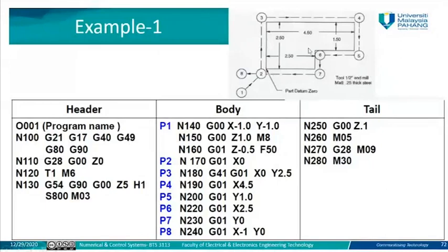Then for this part, for example, you need to go inside in y, then go right, then down, left, down, and return back to the reference point. So it's not that difficult to test using the simulator, but just try to use the correct dimensions suitable for the machine. Also, for example, if it is given in inches, just use millimeters, or change your setting to millimeters and so on.